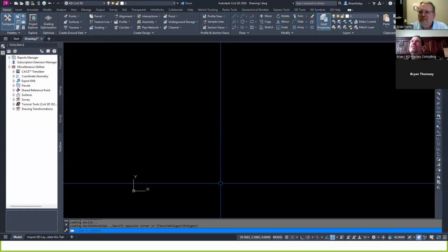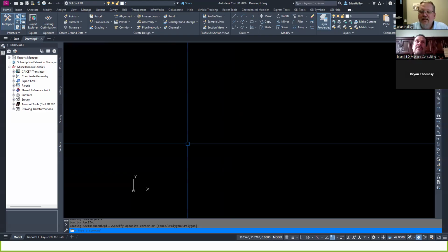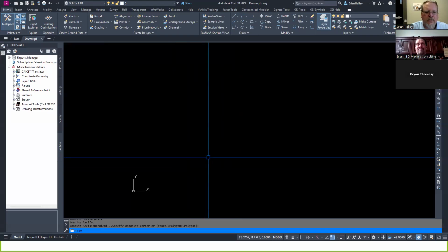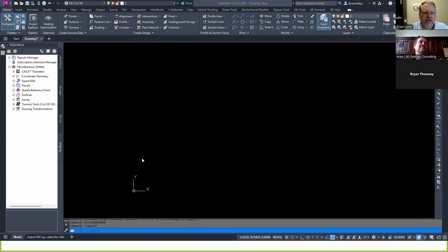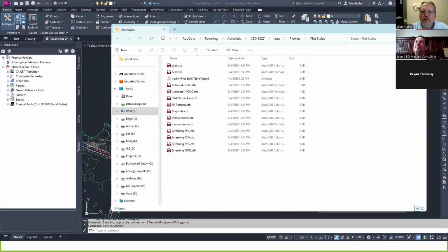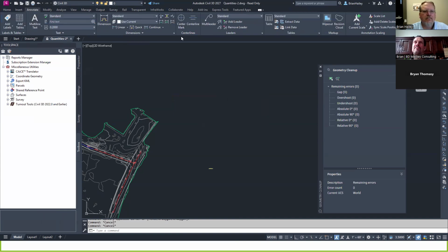So you got one from Quinn asking, what are the benefits and cons to switching from SHX fonts to TTF fonts? Oh, font question. Ignore SHX, just go with TTFs. Yeah, true type fonts. You lose the ability to make them bolder with your layers, but other than that, the true type font has definitely been a huge asset for us moving to.